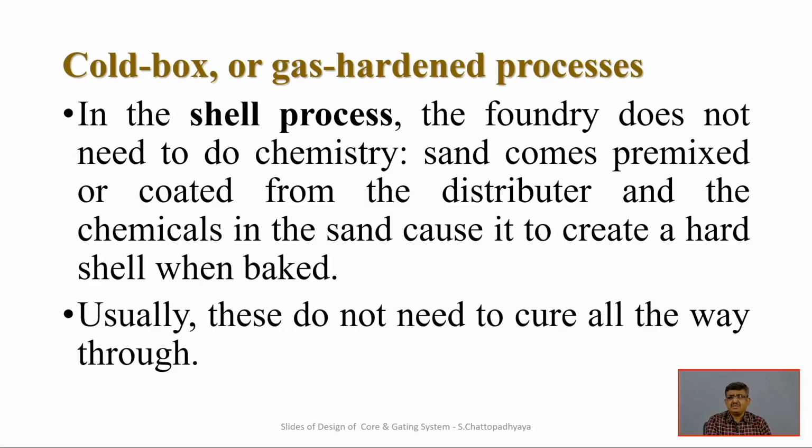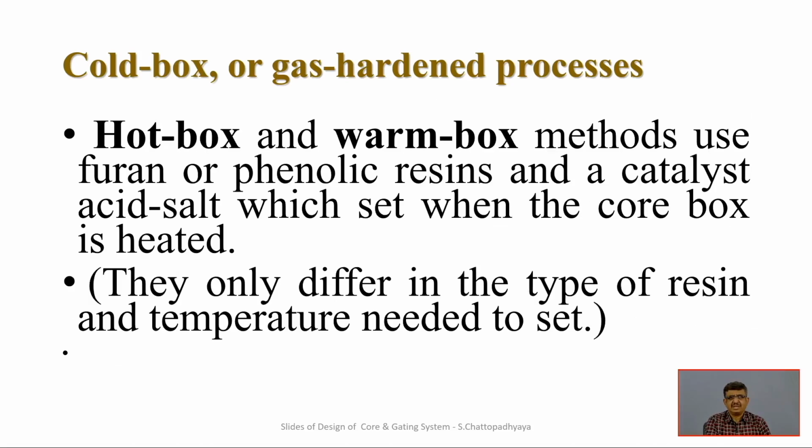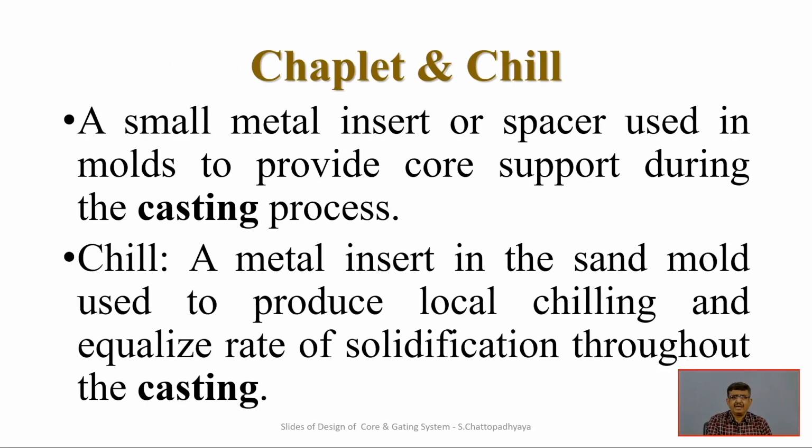And usually these do not need to cure all the way, only hardening, and that will be a self-binding activity. So, there are different boxes, hot boxes and warm boxes. Use those things at elevated temperature to ensure that kind of bonding in the chemical environment. Then other things which are associated with these core making and placement processes are chaplets and chills.